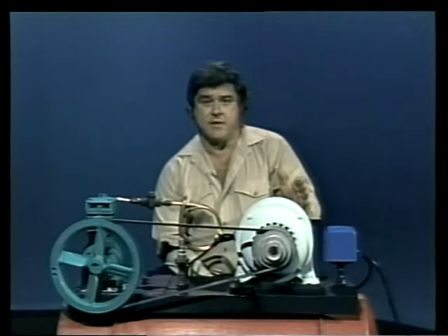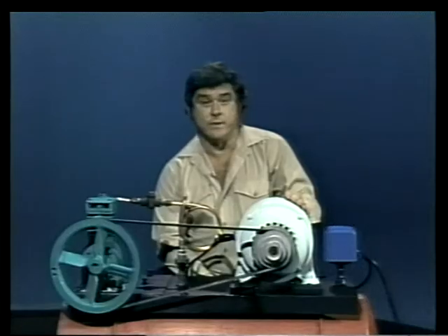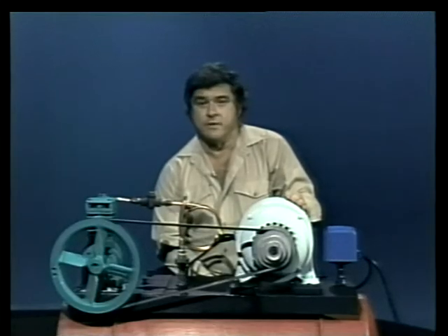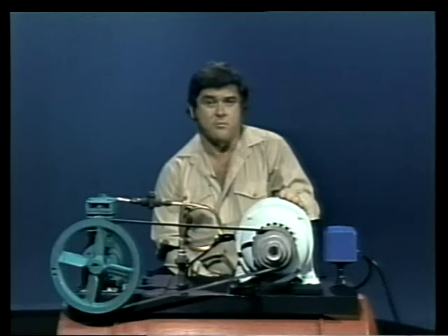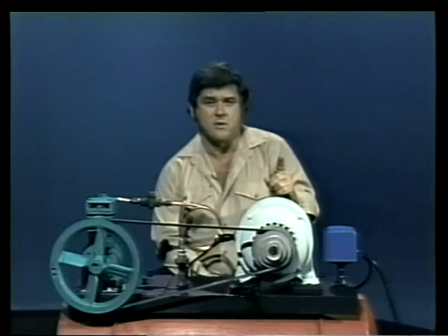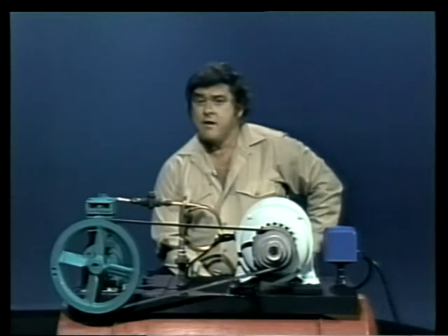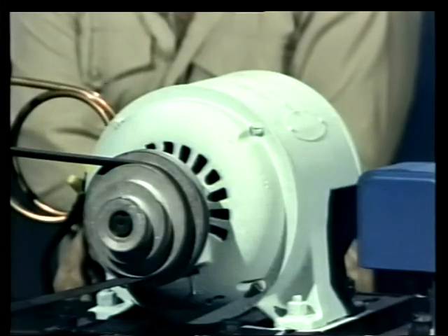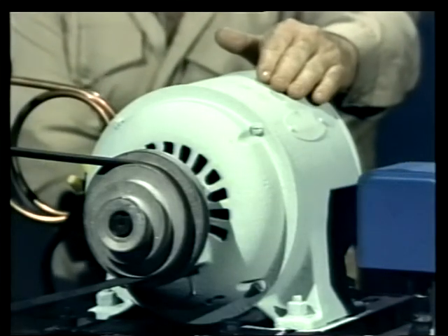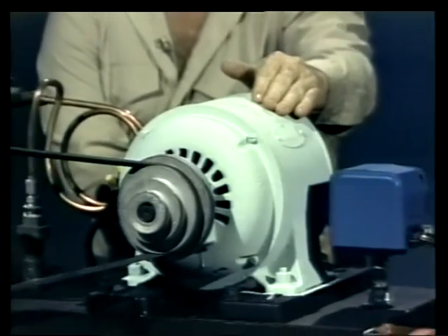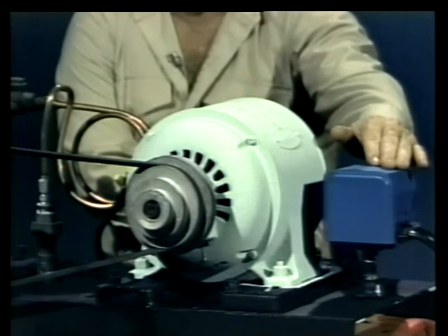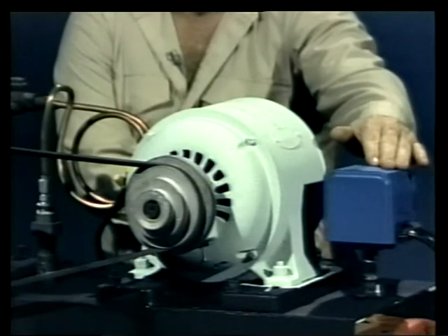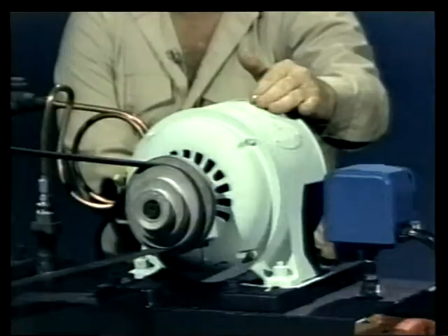and off. As air is used, the compressor will keep filling the receiver. When air is not being used, the compressor will fill the receiver up to full capacity, then shut off. This kind of on-off cycling control is the most common of all pressure controls, especially on small compressors like this one. There are some other ways to do it. One alternative is to vary the speed of the motor. As receiver pressure increases, a pressure-sensing device slows the motor down so the compressor won't put out as much air. When pressure starts to drop, the device makes the motor speed up to match the new demand.